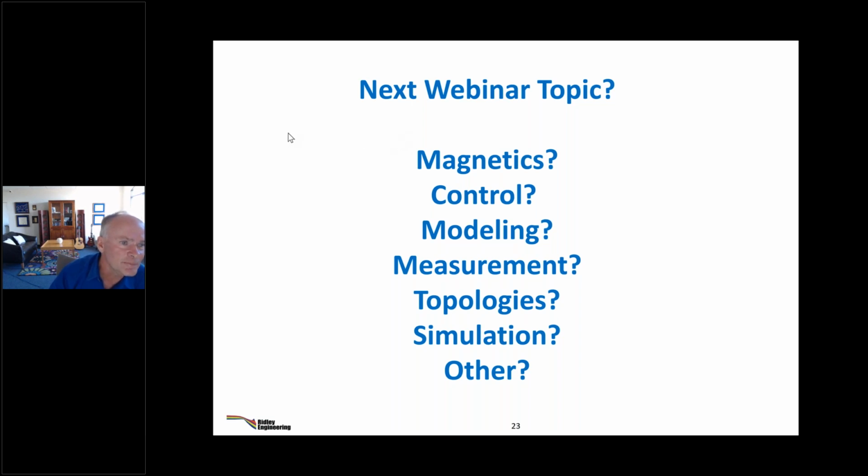Type of compensation? Well, current mode, that's all I can say to that. Unless you can accept slow response, doing a voltage mode control of the LLC is a struggle. Some people will operate their LLC right at the resonance. They don't care about controllability. They just want efficiency. They're not trying to regulate the output voltage. They're regulating the input. Sure, you can do that.